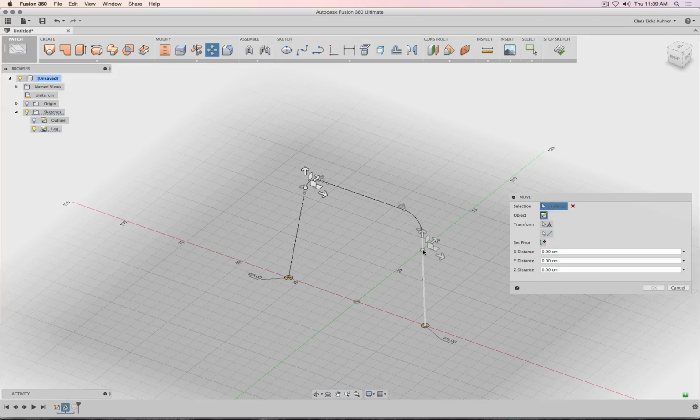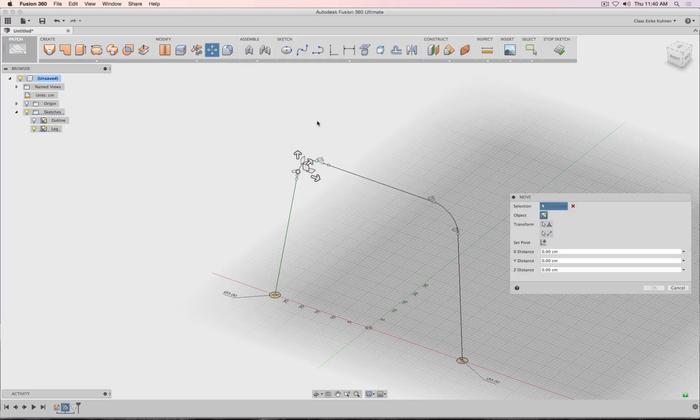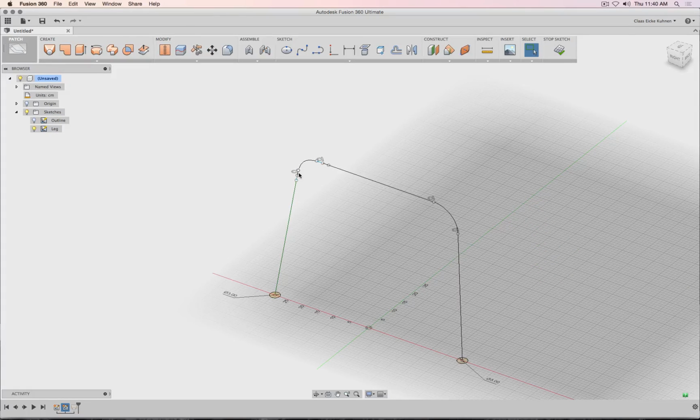And in Fusion, when you adjust this curve, the other curves will react to it as well. So before we can do this, we can simply try this. We select this line, right mouse button, say fix, click our handle there. Let's see. See now, I told the software this line cannot be moved. And then when I adjust actually this handle, the software understands not to manipulate this line.